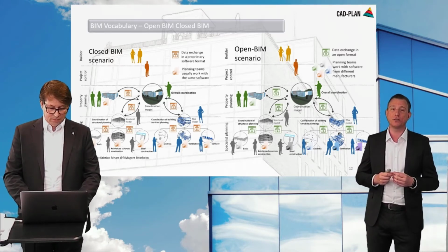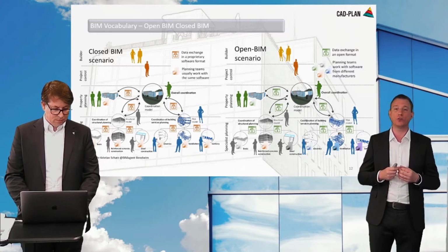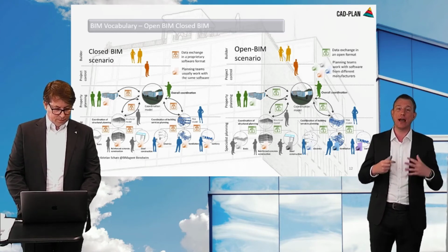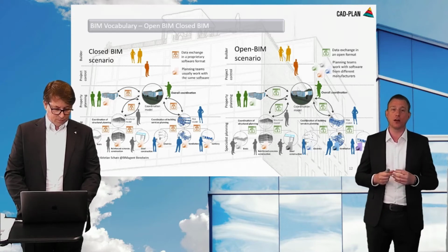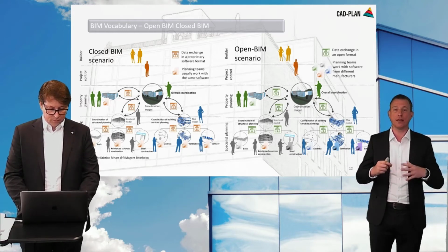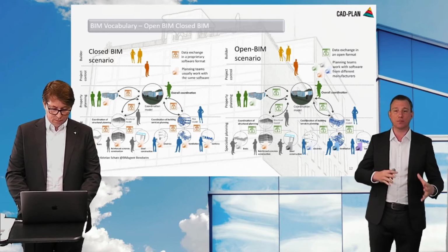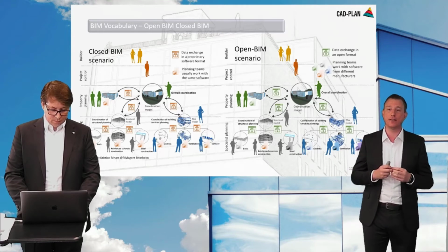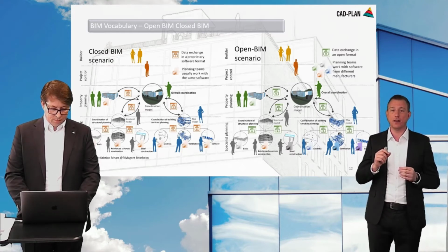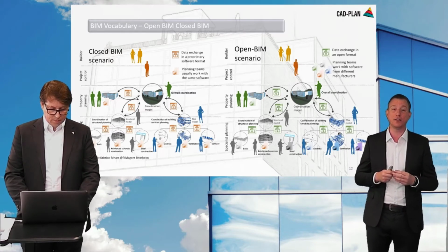The scenario on the right shows an open BIM scenario. This means that open formats are allowed, so the software you use is not bound. For example, the exchange with IFC, Industry Foundation Classes, a globally open and valid format. At the beginning, we discussed that software can support you in BIM. This means that the model with the required information can be exported as an IFC file and can flow into the information management. But be careful, even an IFC file has to be checked to see whether the required information is included in the file. This must be tested correctly.